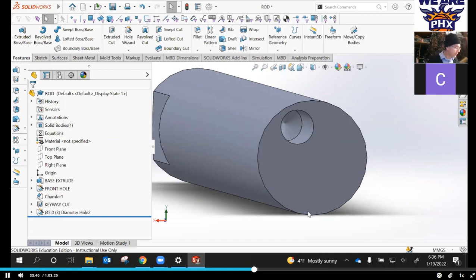All right, so now we're going to attach this hole to the center of the circle. Okay, back face, click edit paste. If needed, delete the old constraint. Rename the feature and then expand it, edit the sketch, locate the back hole, insert a coincident.